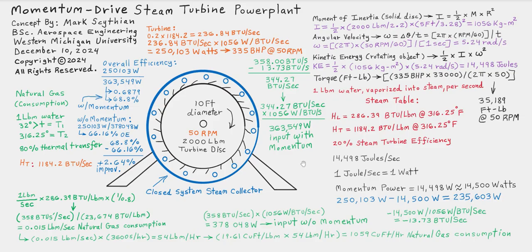So if you have an industry standard that you need a minimum RPM, we certainly have the torque to put a gear reduction or a gear step up, a reduction system or step up system. So in this case, we probably need a step up system that allows this to drive a much smaller drive going to a much larger drive. So there could be a larger ring gear here, and then we could have a very tiny gear, or maybe half the size.